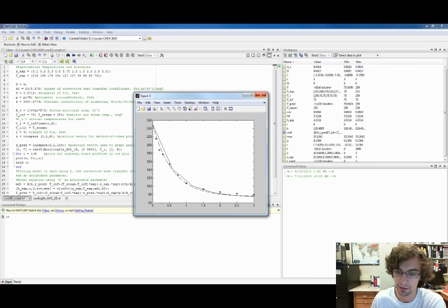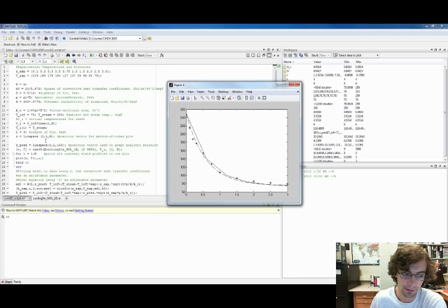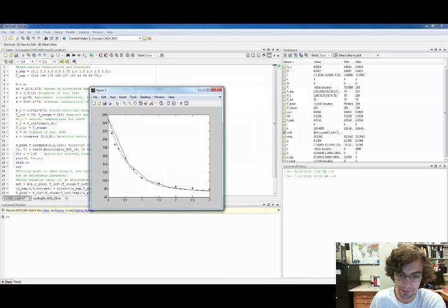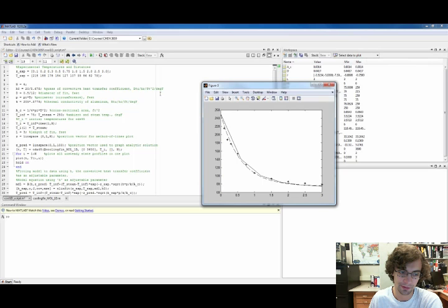If you figure out the heat dissipation at different locations, then you can basically instantly know the fin efficiency, because it's defined as the heat it actually dissipates over the maximum heat it could dissipate if the entire fin were at the base temperature, in this case 250 degrees Fahrenheit.